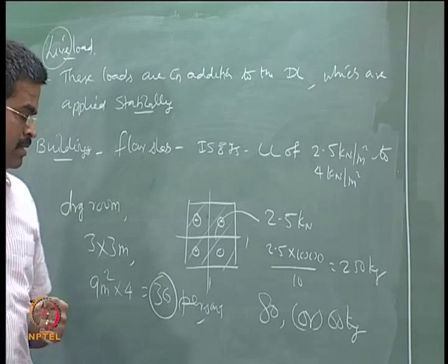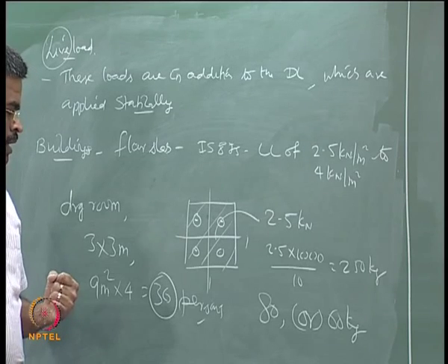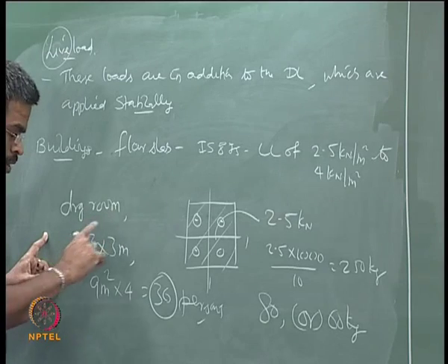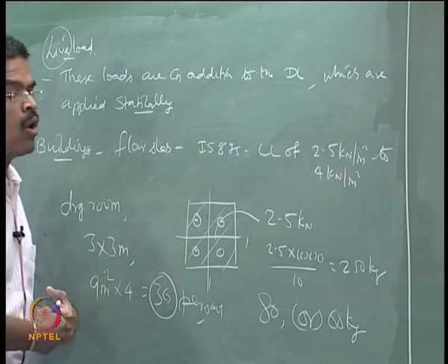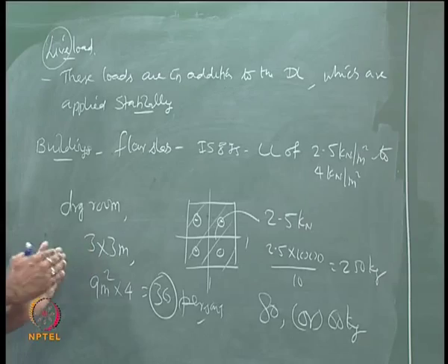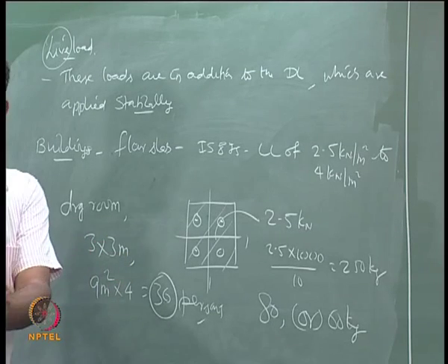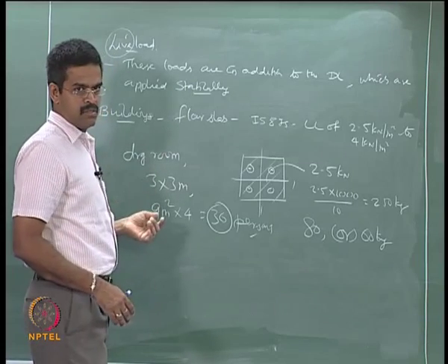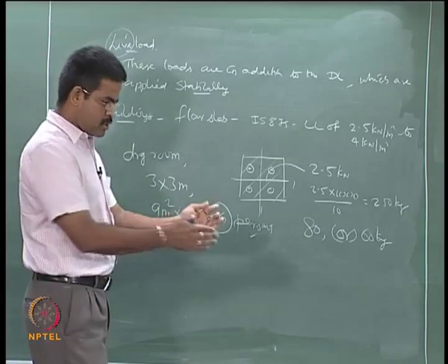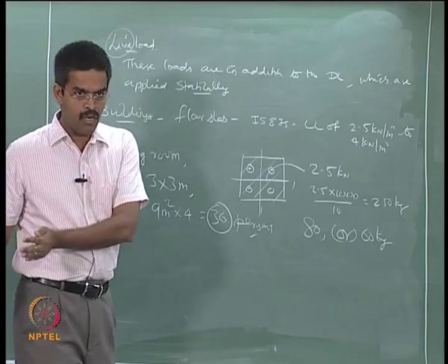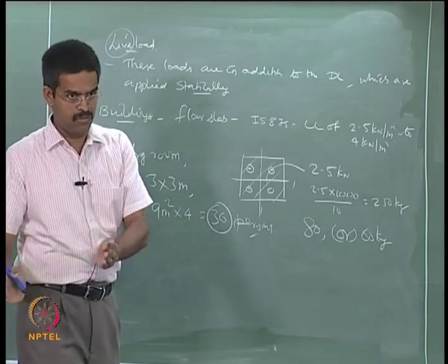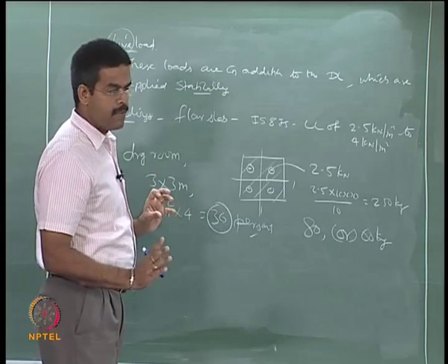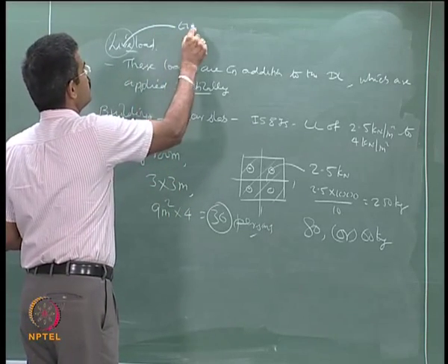Okay. But in a building, in a floor slab, in a drawing room like this, all the load will not be acting continuously throughout the day, because the load pattern will shift from drawing room to kitchen to dining to bedroom to service areas, etc. For example, in an institution, in a school, classroom to library to restrooms to corridors to play areas, etc. There will be a shift depending upon the timing of operation. So, in real sense, if you see, live load should be time dependent.